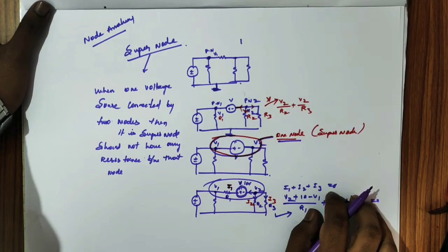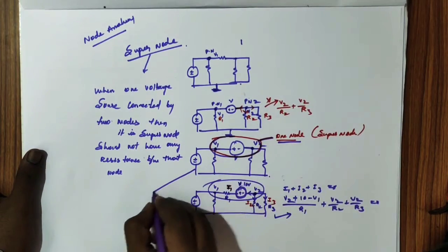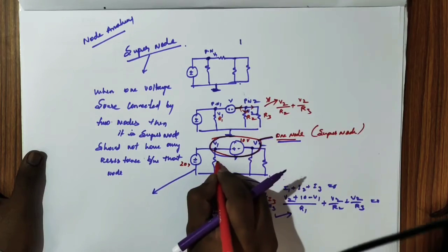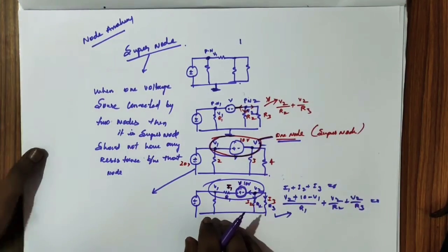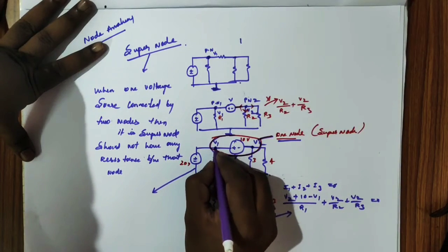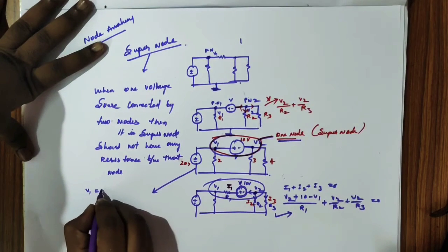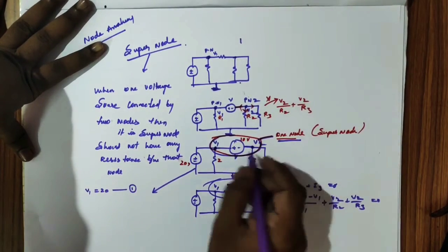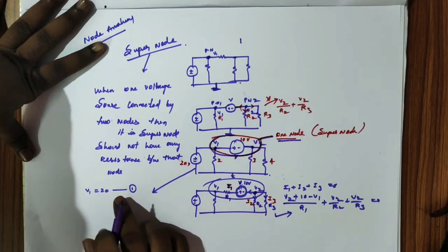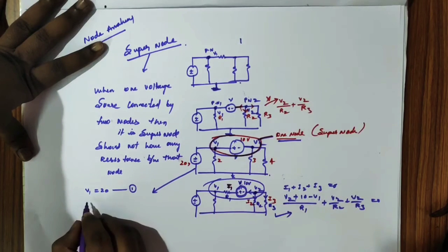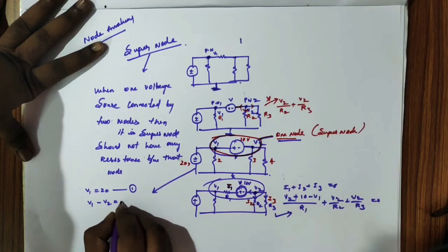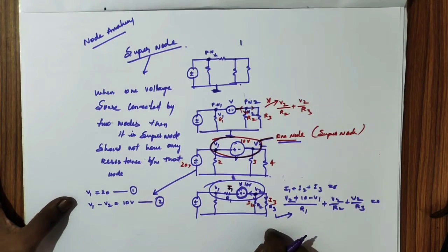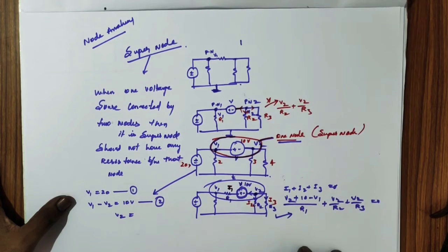So how do we solve this? In this example, let us take 20 volts and 10 volts, with 2 ohms, 3 ohms and 4 ohms. Now we start at this node, as is our habit. Directly we have a voltage source here, therefore V1 equals 10 volts, taking this as ground. This is equation 1. Keeping this as a supernode, we have V1 minus V2 equal to 10 volts. This is equation 2. Substituting these two equations, you will get V2, so you get V1 and V2 directly.